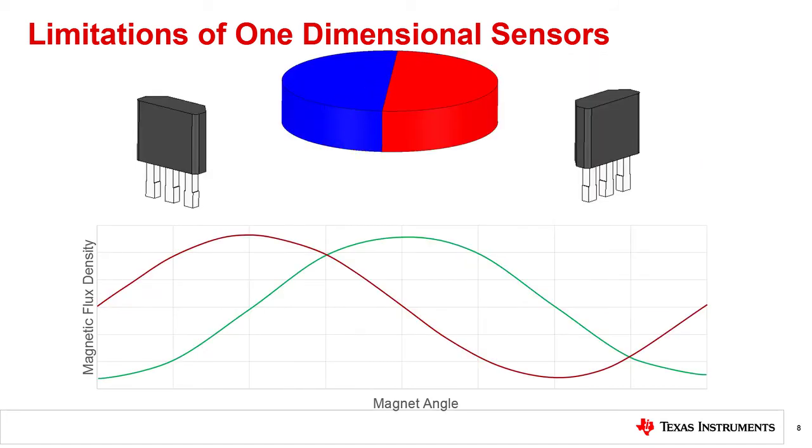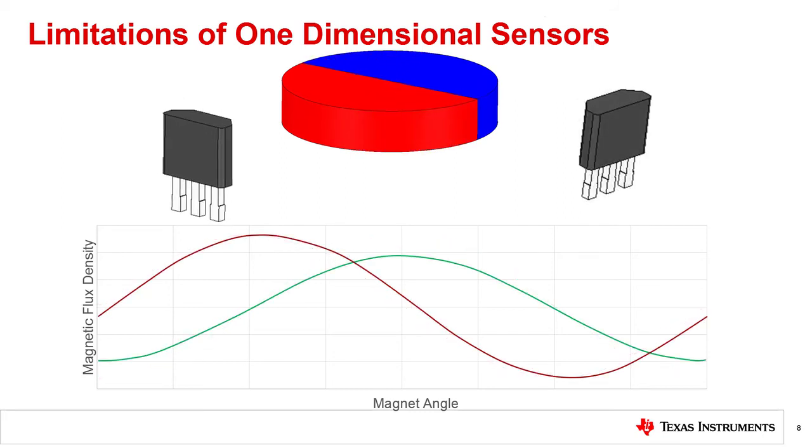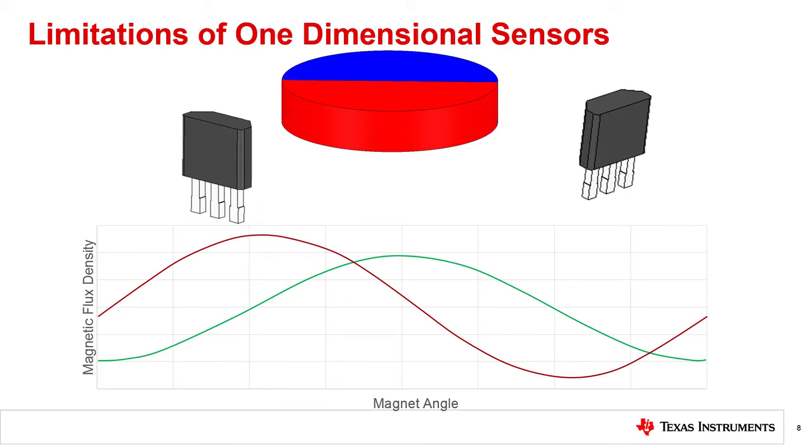Other applications may use two sensors carefully placed for matching inputs produced by a rotating magnet. This function requires two sensors 90 degrees separated, and is an excellent way to monitor angle. Misalignments and other factors such as sensitivity mismatch can produce measurement errors which will affect system performance. Here we observe that the magnitude and alignment errors will impact the ideal 90-degree phase shift between the outputs, which will ultimately define system accuracy.